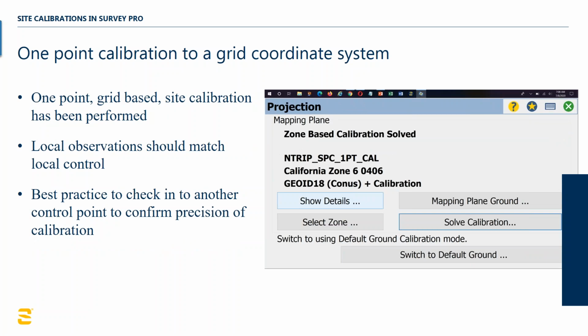So here you can see that using the single point, the one solved by Opus versus the one that I got as a result of corrections from a local CORS station, and I've solved it. It's a simple translation in this regard. And with that in mind, you would say, so I can use the translation routine. We'll talk about that.